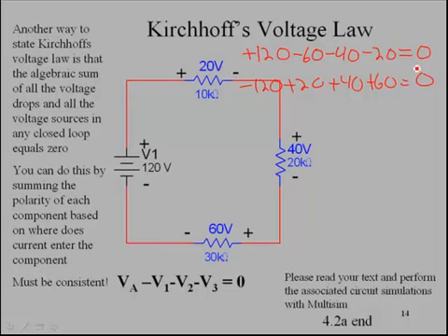Now I'm going to encourage you to read the text on this particular subject, and there are several circuit simulations that you can do in Multisim to prove this, and you need to be able to go in with the simulation and attach a multimeter and actually measure these drops and see for yourself that this is the way it is, and that Kirchhoff's voltage law does make sense. And if you algebraically sum all the values in a series circuit, the sum will be 0.